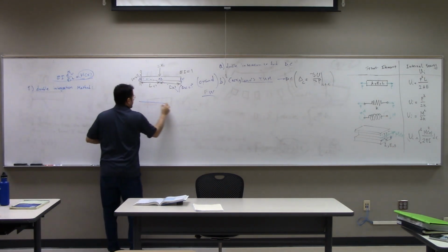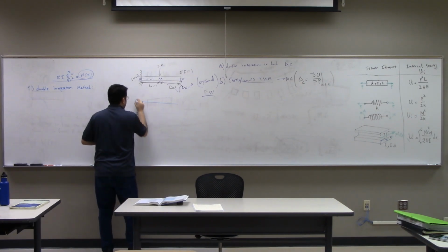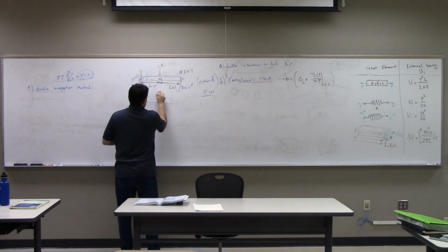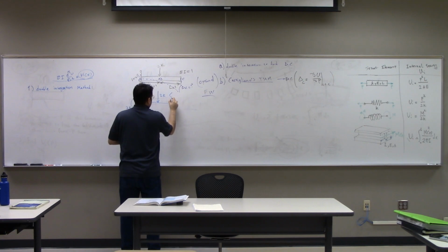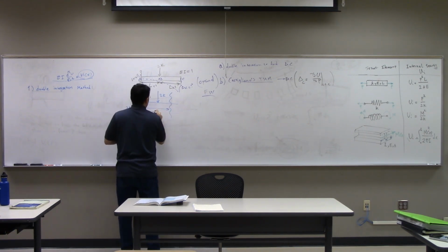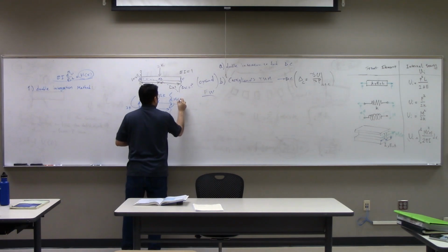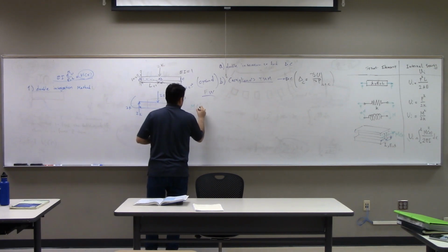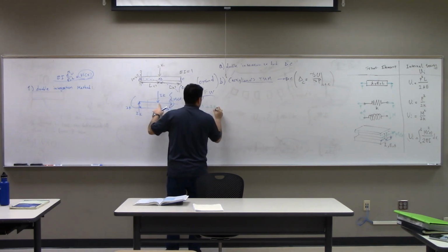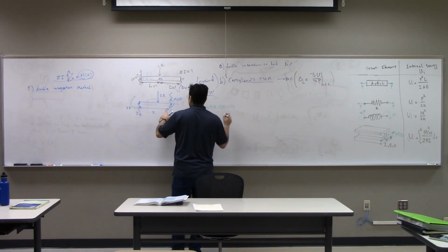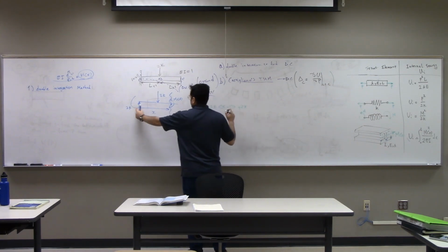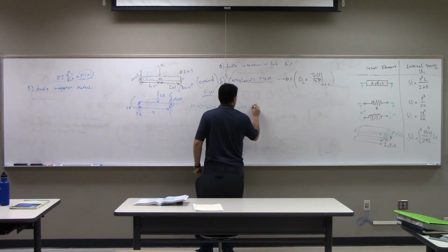So if I make a cut, then you have 2k here, and you cut it somewhere on the left, Mx, and you have V. Then the sum of moments gives Mx plus 2k times the Heaviside function of x minus 1, plus 2k kilonewton meter, minus 2k times x, equals 0.